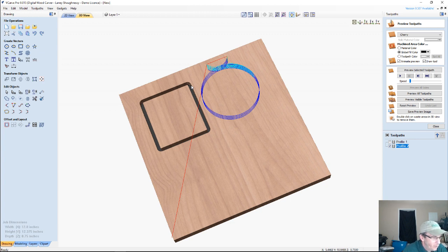and we're not just plunging in and taking a full plunge all the way around, which causes that chipping and fraying and stuff, especially if we're using an upcut bit. By the way, if we're cutting in plywood, we should be using a downcut spiral or a compression end mill, but a downcut spiral is fine enough, because you don't want any of that chipping. Even a straight 2-flute or 3-flute bit is great for plywood as well too. But an upcut spiral, definitely not. You don't want an upcut bit, because that's going to definitely cause chipping.